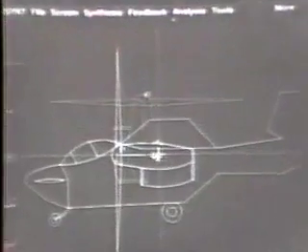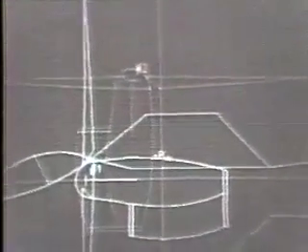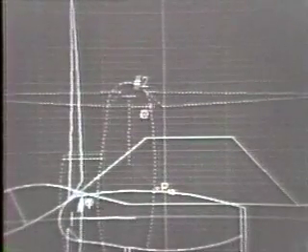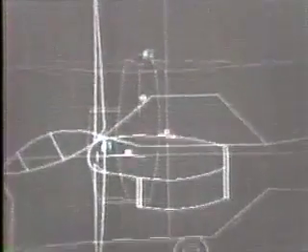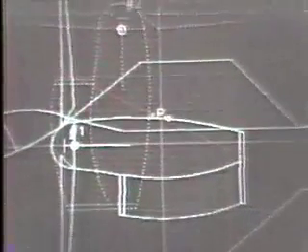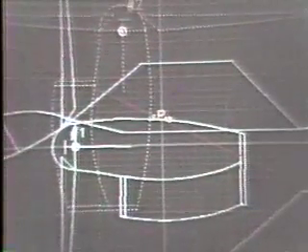As the rotor tilts, it must shift in a carefully controlled way so as to keep the lift and gravity forces in balance. At this point, the designer has already specified two design positions for the rotor and is now in the process of studying various possibilities for where a moving pivot for a 4-bar linkage might be located. This first moving pivot will be used to guide one point of the rotor exactly through the two design positions.